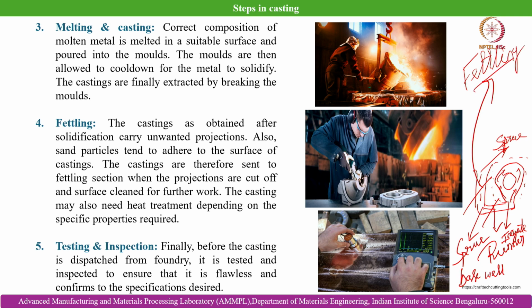So it is also an important step in the casting process, because it is necessary to remove them effectively, and also it should not end up making a notch over the cast object, because then that can serve as a preferential site for crack nucleation and fatigue failure, provided the component is subjected to fatigue loading. So that is why fettling is another important step of the casting process.